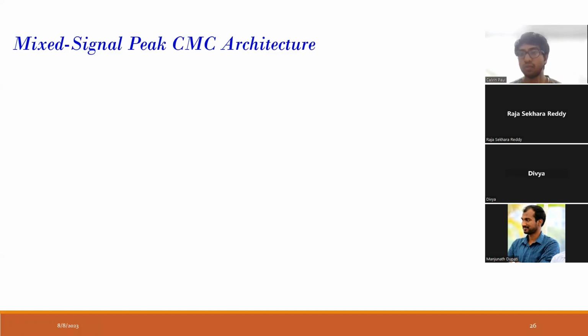So if you remember, in voltage mode control, we are sampling the output voltage. The output voltage is sampled. We are not sampling the inductor current, and we are using only the output voltage information to control our DC-DC converter. It is a single loop control, which I spoke about last week. Now, in current mode control, it is a two loop control. There's an inner current loop and there's an outer voltage loop.